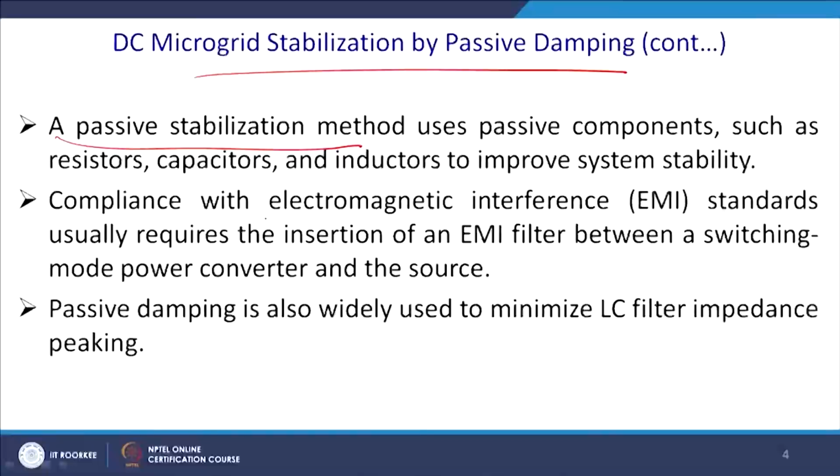There is also the challenge of compliance with electromagnetic interference standards. Once you have sustained oscillation, you generally have a huge problem of EMI and EMC, and generally once you suppress one entity, you will find that you have aggravated another.